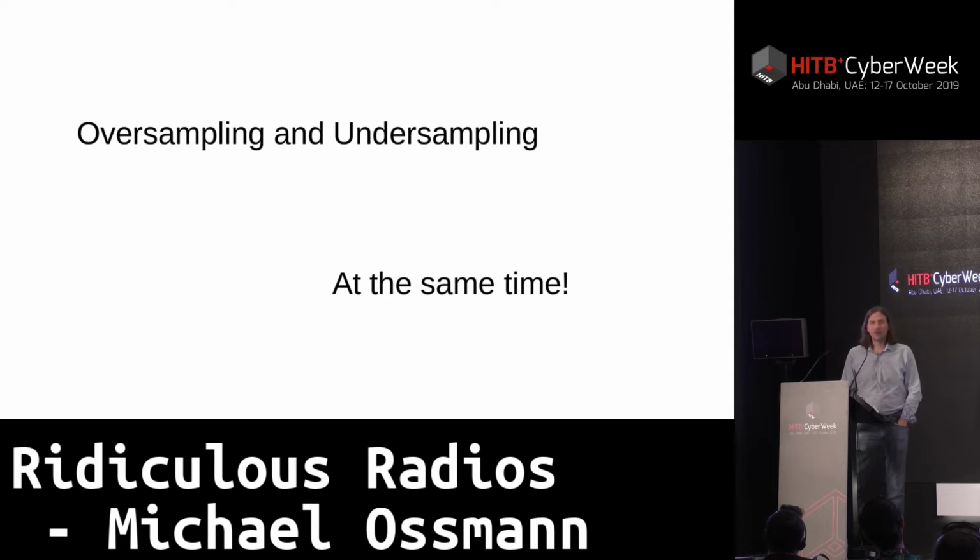So in this case, we're actually oversampling and undersampling at the same time, which sounds ridiculous, but it's truly what we're doing. We're oversampling in the sense of we're using a much higher sample rate than necessary for the bandwidth of our signal. So in the frequency domain, we're reducing the amount of bandwidth by reducing our sample rate, and that gains dynamic range. That's what oversampling is.